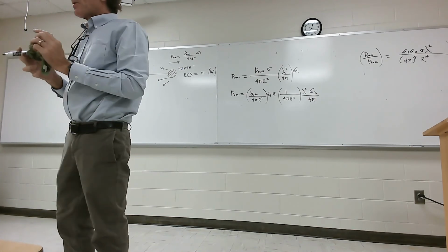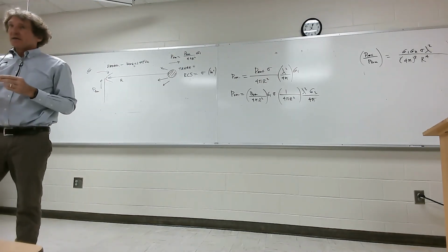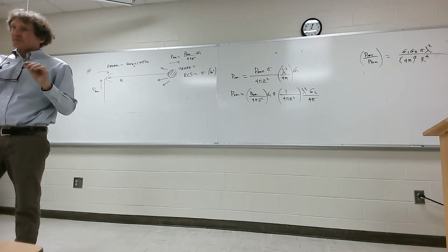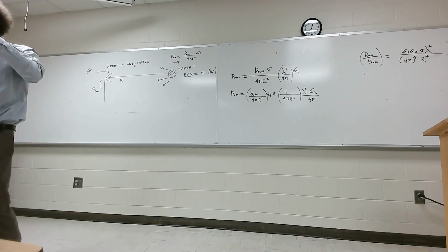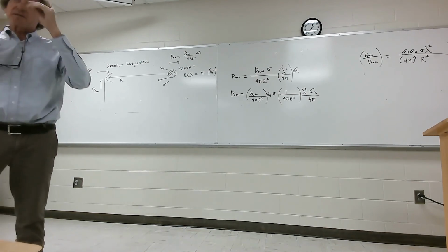And for the most part, if an object is many wavelengths across, its electrical size to an antenna is about the physical size that your eye sees. So if you have something with a cross-section of 1 meter squared and a wavelength like a centimeter, electrically it's about 1 meter squared in terms of its actual electrical size, assuming it's a conductor.